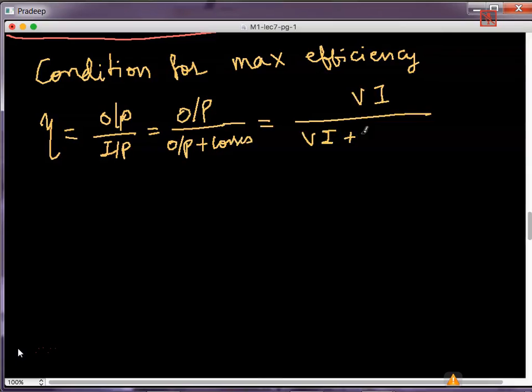Now what are the losses? One loss is WC, that is constant power loss, that is friction and iron loss and everything, plus another loss is IA square RA. Now what about shunt field loss? That also is considered inside the WC itself. The shunt power losses also is in this. Now, because the armature current is almost equal to the load current, because shunt current will be percentage wise less, IA is almost equal to I.